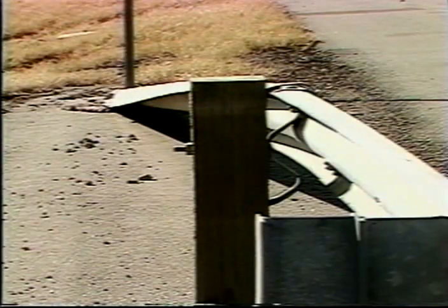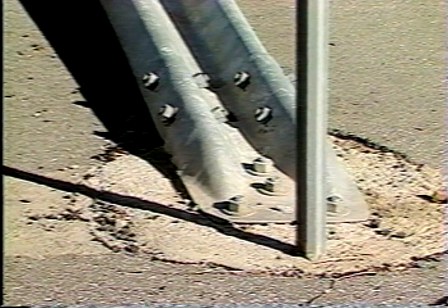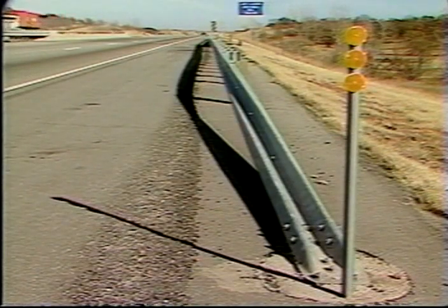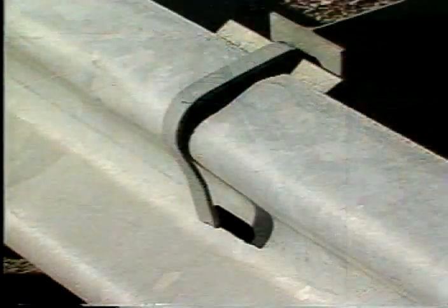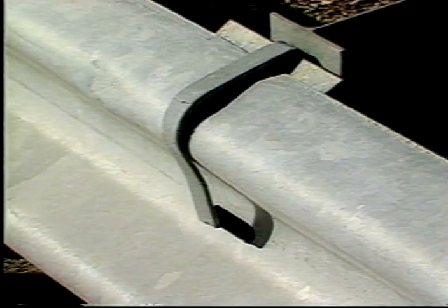The twisted and turned down end treatment should be flared out at least 2 feet, preferably 4 feet, to be operationally functional. The turned down end of the system should be anchored by 4 bolts to a concrete footing that's either at or below grade level. As mentioned earlier, the rail is intended to release from the first post and lie down. To bring the required quick release, several systems have been developed that work like these galvanized steel clips.